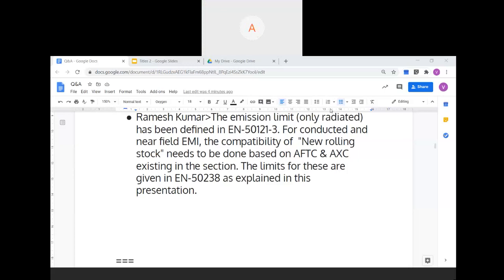Mr. Akhilesh, I just wanted to know, since we have worked on the locomotive, this TCAS is also coming and ETCS both are coming. Sir, will it be possible for fixing both the equipment on the same locomotive? Sir, I was finding it difficult to place one. But if there is a will, there could be a way. We'll have to displace a lot of onboard equipment because then you will probably have two DMIs and two sets of odometry, two sets of Balise transmission. Or the brake system can be common.